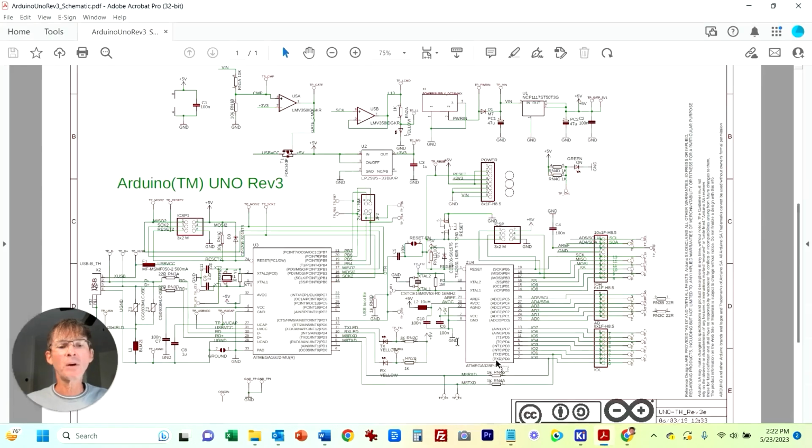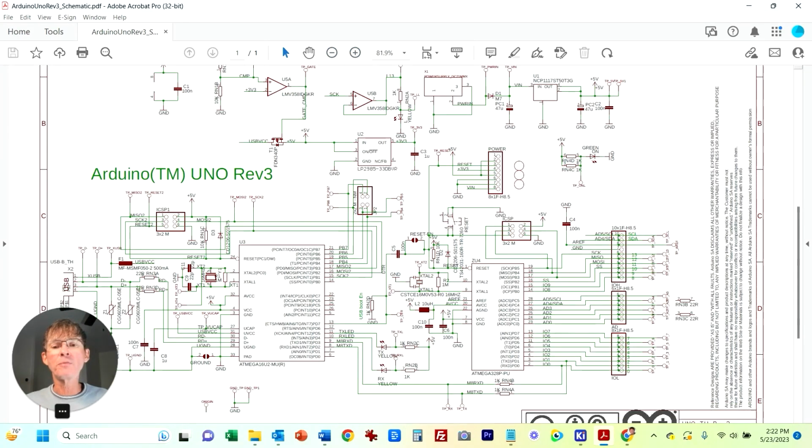So I'm going to switch back to our schematic here, and we'll just start with how the data flows. Data comes into the USB, and we're going to cover this first microcontroller that serves as the USB to UART converter. Then I'll switch over and we'll work on this part of the schematic for the primary microcontroller, and then we'll jump up here and do this comparator, buffer, and the various voltage regulators, and any of the headers that you want to do also.